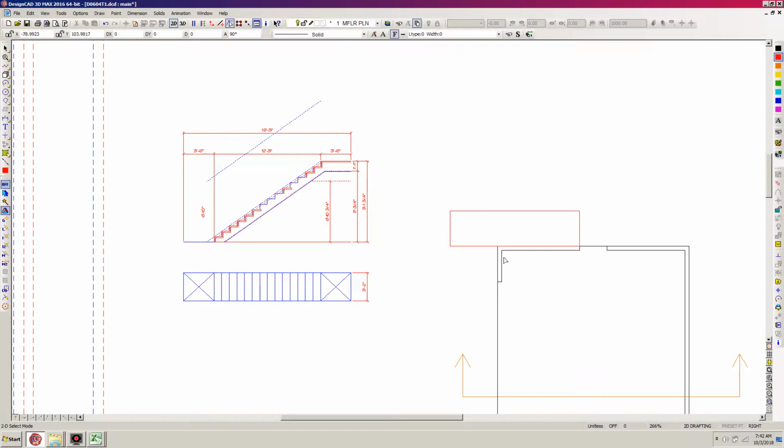So there's my rectangle. So that means that the stair, and we'll also have a concrete landing out here, and we'll have a landing at the top. But this stair will project substantially beyond the garage there. So an easy way to do that is, I'll just do a new stair design. 10.5 inch treads are, like I said, a pretty comfortable stair for this situation. And we're going to have a landing.